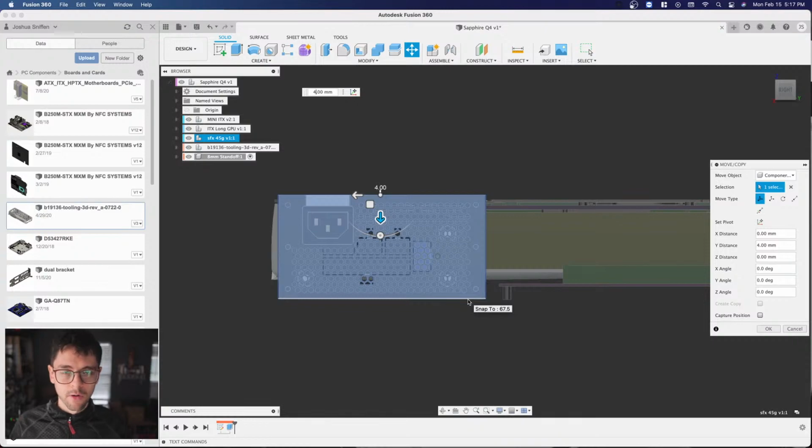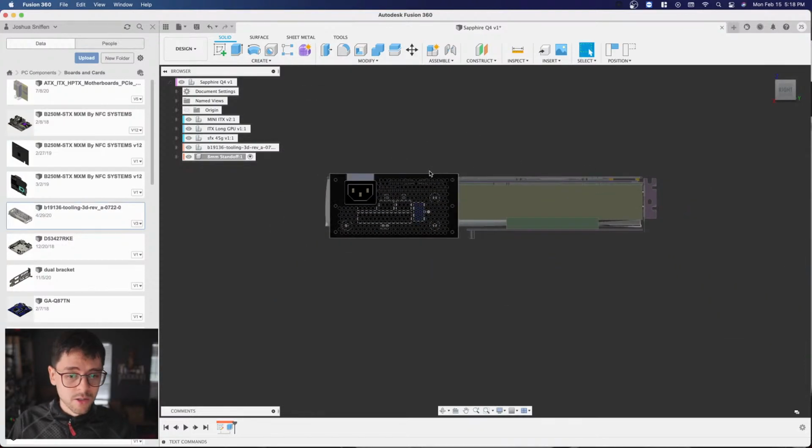You never, never, never want to make a computer case that you're making by hand or with simple tooling to the exact tolerances that you'll look up online. You want to go extra, extra loose for every part and panel and component. It will look really big in the computer, the gaps will look nasty, but in real life you won't notice it at all, and it will really make things handy because in the real world, things do not come out like they do in the computer, and that's something that's very important to learn. Otherwise, you could spend a lot of money fixing this stuff.